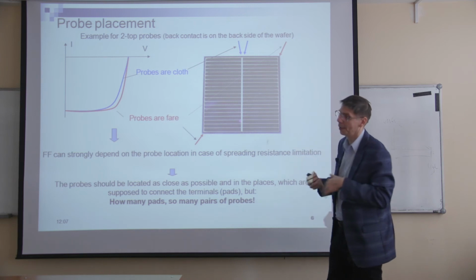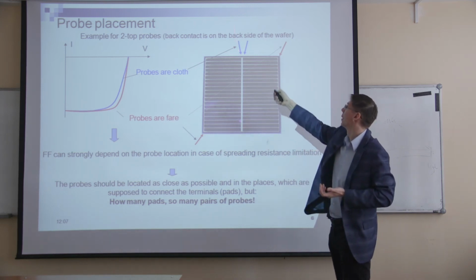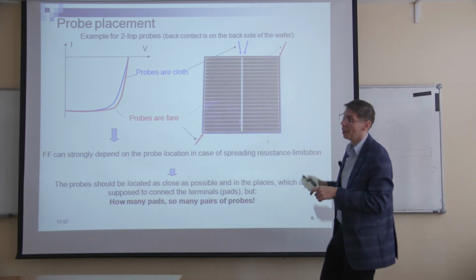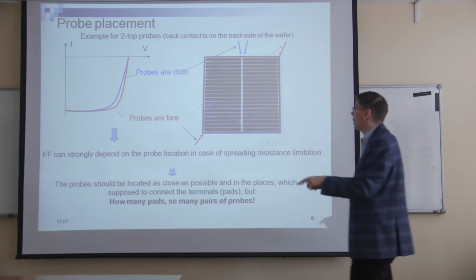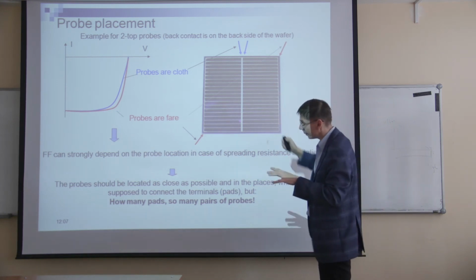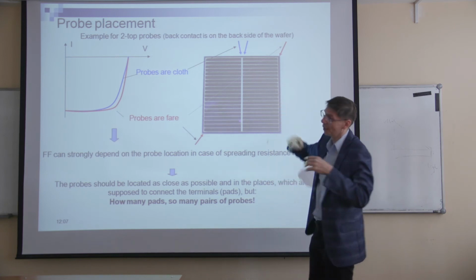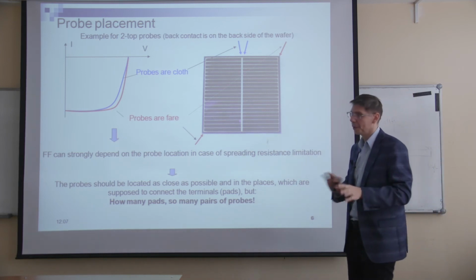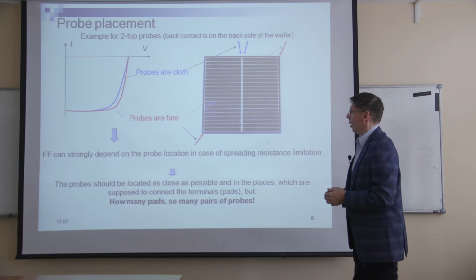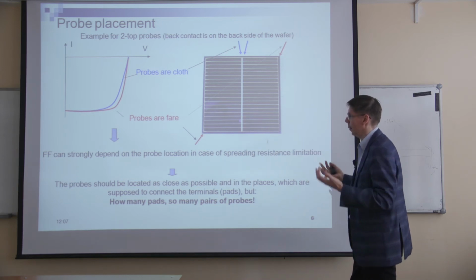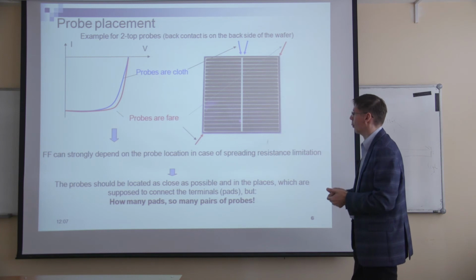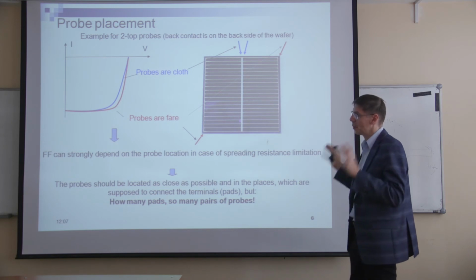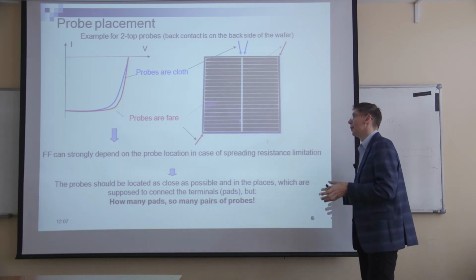The tip for the voltage measurement is connected to another tip for the voltage measurement. The tip for the current measurement is connected to another. Not the cross connection, I mean, you cannot connect a tip for the current measurement with the tip for the voltage measurement. In this case, you are not in a four wire measurement condition, so it would be two wire.